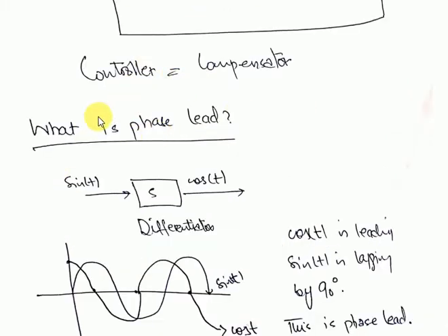Okay, students, so what is phase lead? As we will study lead compensator and lag compensator, we must know what is lead and what is lag. This is the basic concept we learned in ninth class, what is phase lead. If we have a sinusoidal sine input and it passes through a differentiator, that is s. You know that we call a differentiator s in the s domain and an integral 1 by s. So when a sine wave is passing through a differentiator,